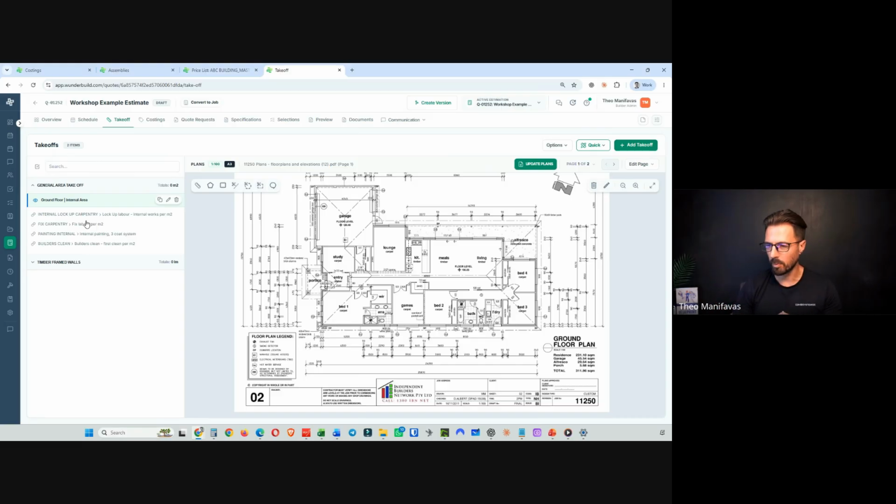So it's little things like this where you need to think it through when you're building it out. And even though something might seem like the more efficient way to do something, it may not end up being so efficient, because you might end up measuring again to do a deduction, or you might forget to do a deduction, and then that's not going to help with the accuracy of your estimate.